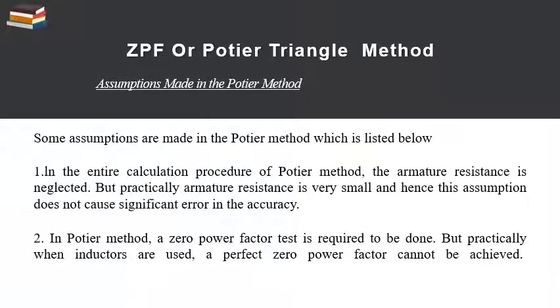Number 2. In Potier method, a zero power factor test is required to be done. But practically when inductors are used, a perfect zero power factor cannot be achieved.